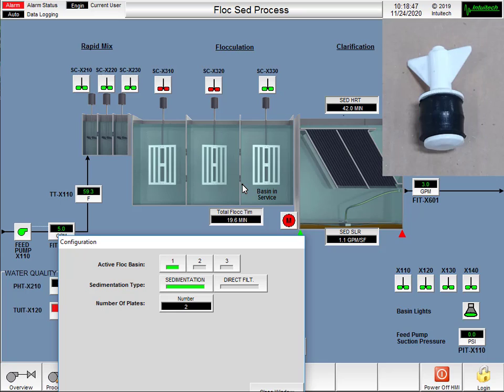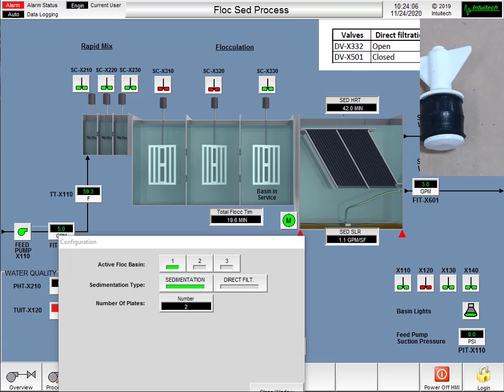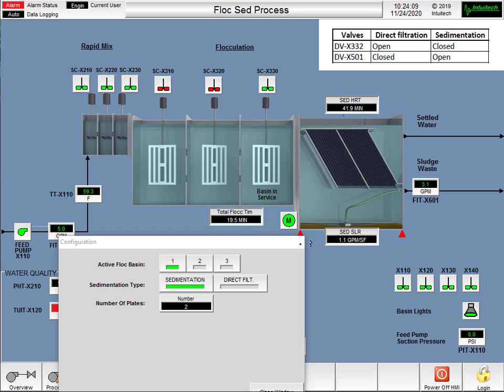This is accomplished by using the provided plug in the spare parts bin. These plugs can be inserted into the baffle holes between the basins. Then you twist the handle to tighten them such that they seal the hole. The second setting is the sedimentation mode. This mode has 2 available settings.